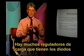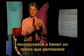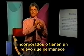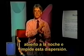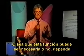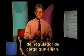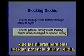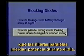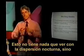There are some charge regulators, in fact, many regulators now, either have diodes built in, or they have a relay or an electronic device that stays open at night and prevents this leakage. So perhaps this function may or may not be necessary, depending on your choice of charge regulator. There's another function for blocking diodes, though. They prevent parallel strings from losing power down damaged strings during the day. This has nothing to do with nighttime leakage.